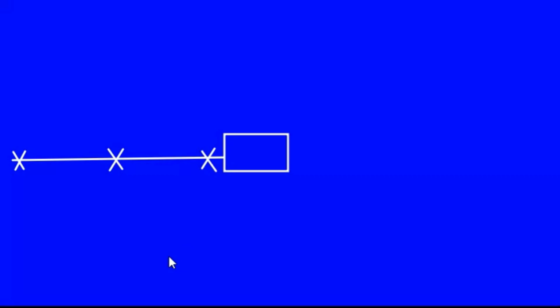Place a cross staff over here, and from a cross staff you can get a perpendicular line which will go ahead over here in such a way that it falls outside the building, right over here. Then we will draw another, bring the cross staff at the other point. You can name it as E and F, or as you feel like. So I'm naming as E and F. So this point is E and the other one is F.